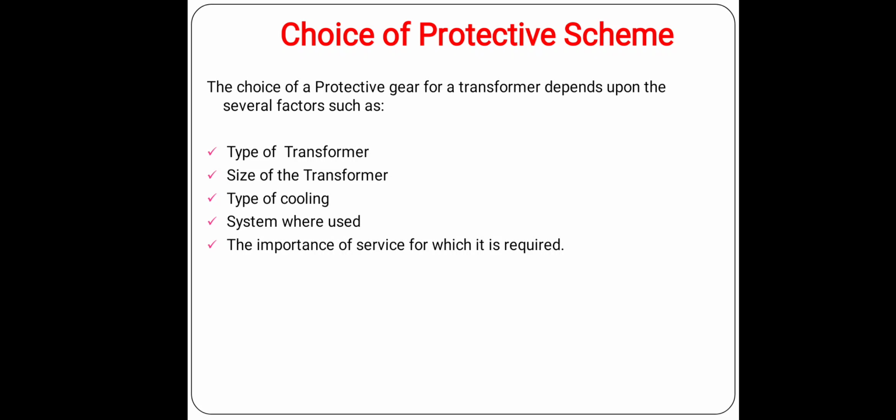for power transformers, the protection is to be provided usually against dangerous overloads and excessive temperature rise. Dangerous overloads may be due to external faults or due to internal ones. External faults, however, are cleared by the relay system outside the transformer within the shortest possible time in order to avoid any danger to the transformer. Hence, the protection for internal faults is to be provided in such power transformers.